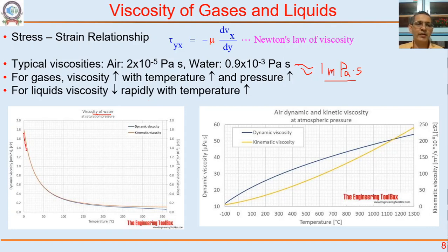So sometimes when you want to transport viscous liquids, you heat them up before transferring. Say you want to transfer some glycerol or polyethylene glycol, some polymers. Rather than transporting them at lower temperature, you might want to heat them up slightly, maybe 70-80 degrees, and then they get transferred easily because their viscosity drops very dramatically with temperature.